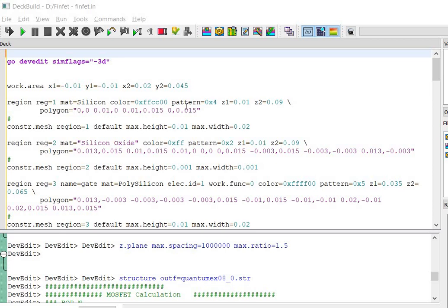The easiest way to use this is the use of hexadecimal values. By starting the number with 0x, each component has a range value from 00, no color, to FF, full color. Next, generic parameter fill pattern. On black and white displays, pattern fills are used instead of colors. There are 18 patterns numbered from 0 to 17. Pattern 0 is for solid and pattern 17 for empty.